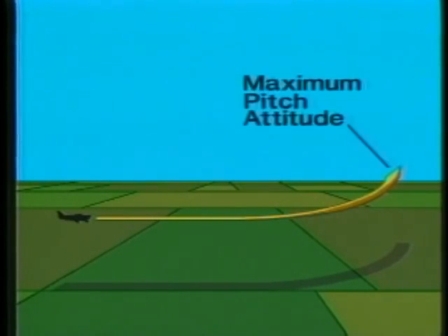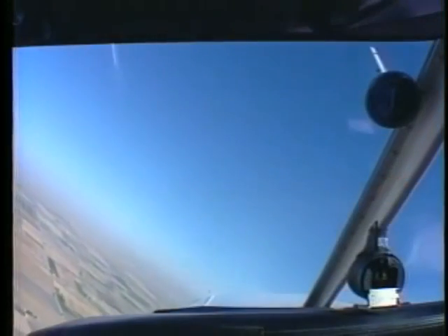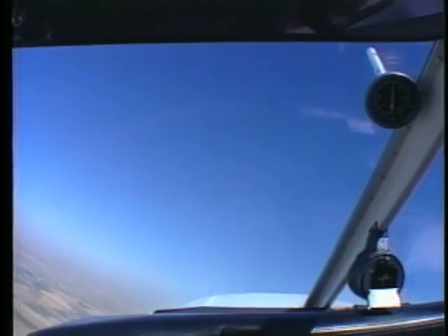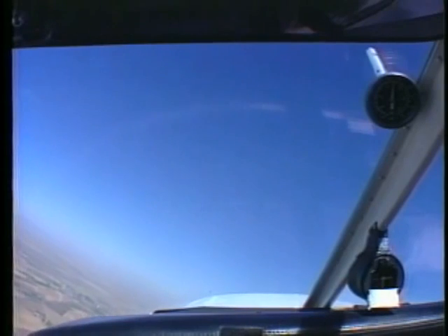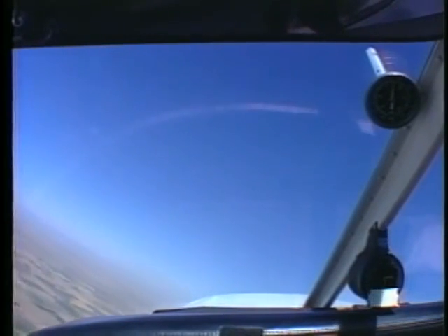During the first 90 degrees of turn, you're concentrating on maintaining the initial 30 degrees of bank while gradually increasing pitch, so that maximum pitch attitude is attained precisely at the 90-degree point. As you pass through the 90-degree point, concentrate on maintaining the nose-high attitude and slowly begin to roll out of the bank so that you reach a wings-level attitude at the 180-degree point.